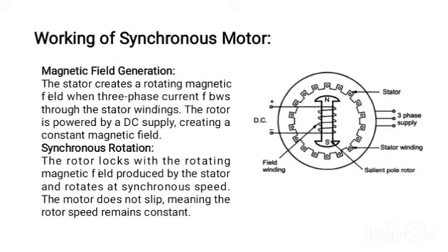The rotor is inside the center of the machine, and the stator acts as the outer frame. On the inner side of the stator, we cut a number of slots, and in between the slots we wind the windings. The windings are made up of copper. The slots and core are made up of cast iron or cast steel.